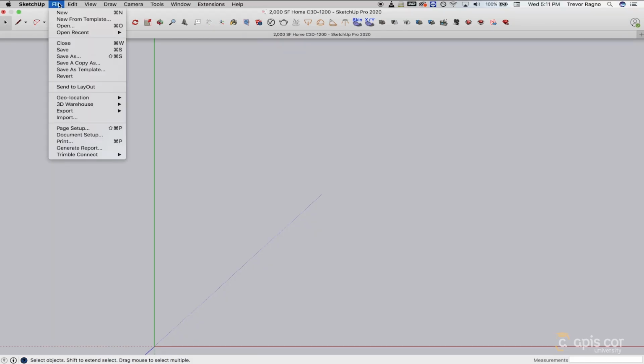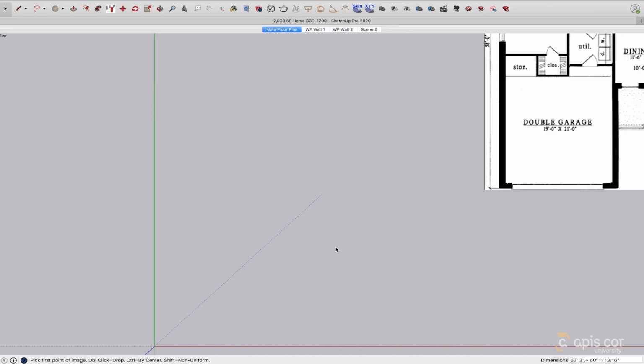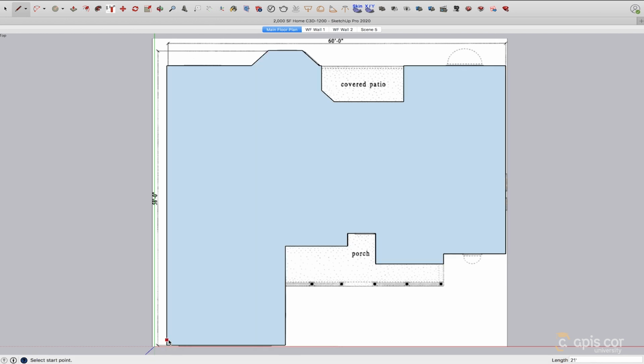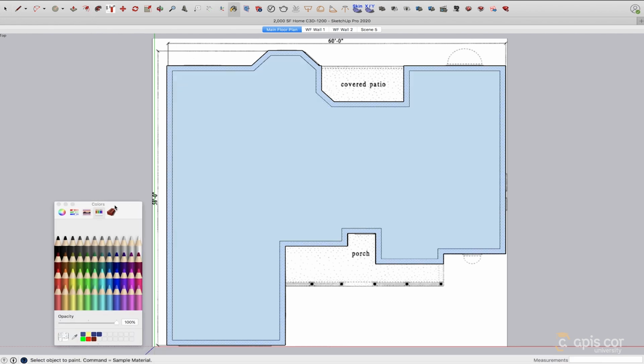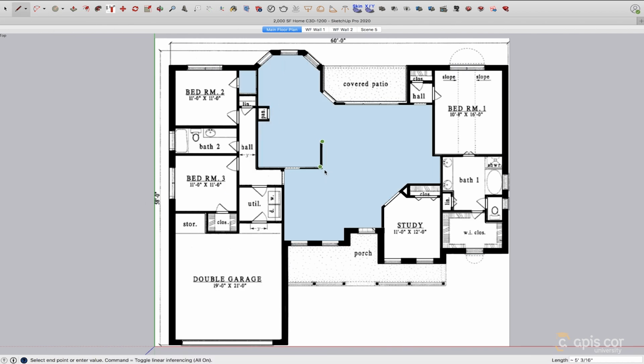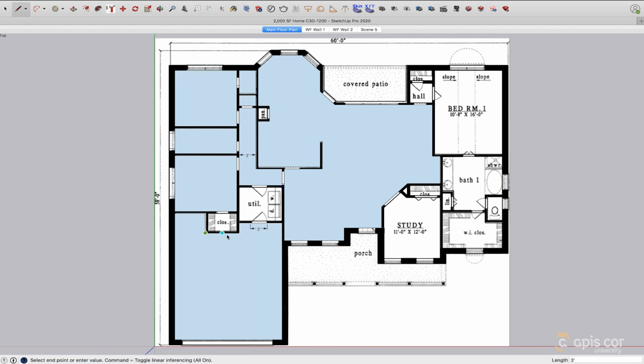And your first step in converting these stick-built home designs into 3D printed home designs is to correct the wall thickness. We can start by importing an image of this floor plan into SketchUp. Then, we can use the line tool to trace the exterior walls of the building. Next, we'll offset the line 12 inches inward to reflect the 12-inch thick exterior walls we chose to use. It appears the exterior walls on the original plan were already about 12 inches thick, so let's add in our windows and doors, and then turn our attention to the interior walls.